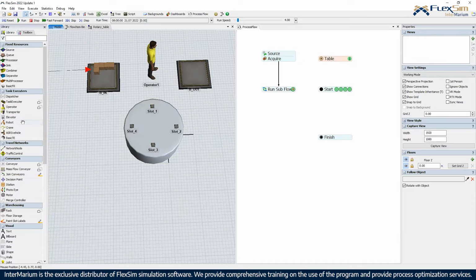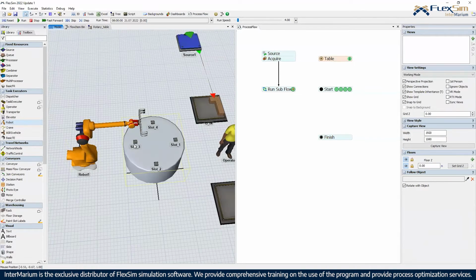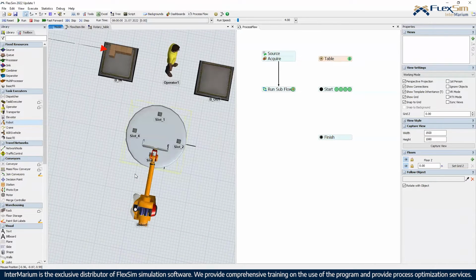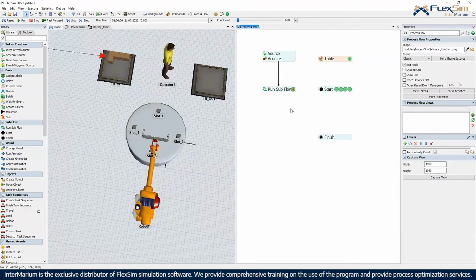And then you have some stations. So for example, somewhere here can be some robot, and he will do some process on the product on this station. So let's say this area is a station. And on this station, in each cycle, a different slot with a different product will enter. So you can think we have 4 slots and also 4 stations. This is the first station, so the first position, second station, second position, third station, and fourth station. And stations are fixed, so they're all at the same place, but the slots with the product will rotate through the stations. So we have to somehow write the logic to know which slot is on which station. Okay, so we have to track it.